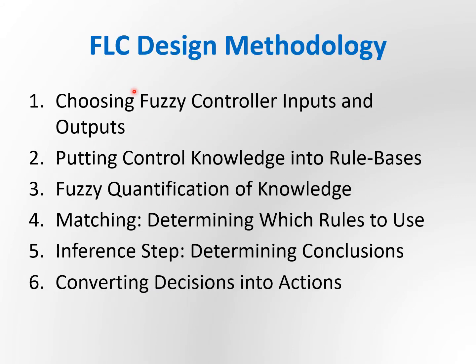Fuzzy logic design methodology. First of all is to choose the fuzzy controller inputs and outputs, and then put the control knowledge into the rule base, then the fuzzy quantification of the knowledge, then matching which rules to use, and then determining the conclusions from the many different rules fired, and finally converting the decision into actual action in the real plant. So this is the methodology that we have to follow.